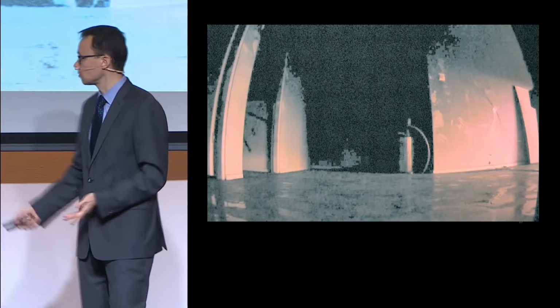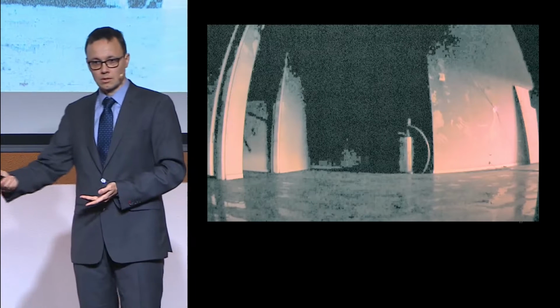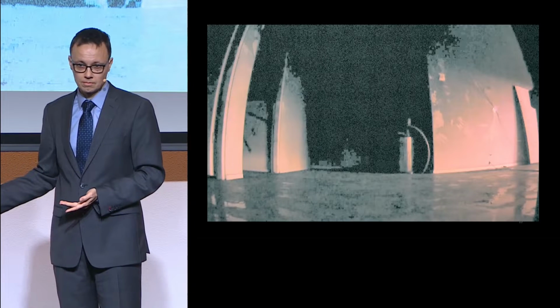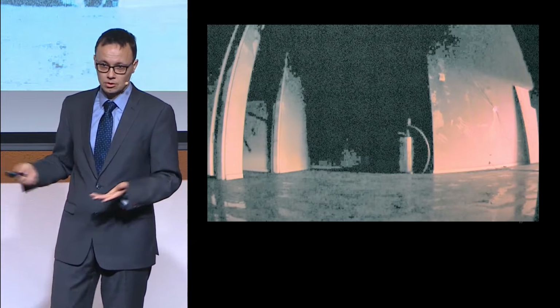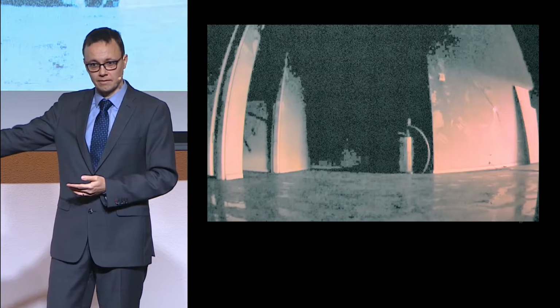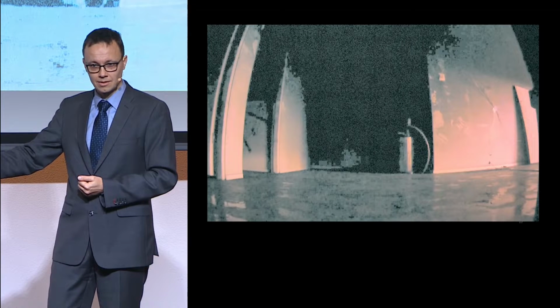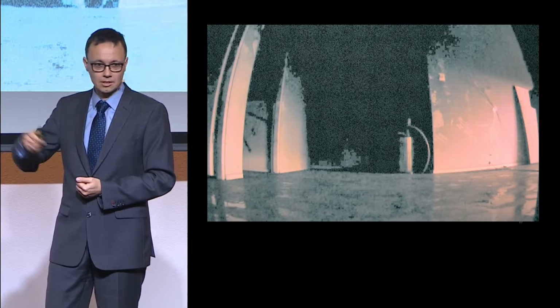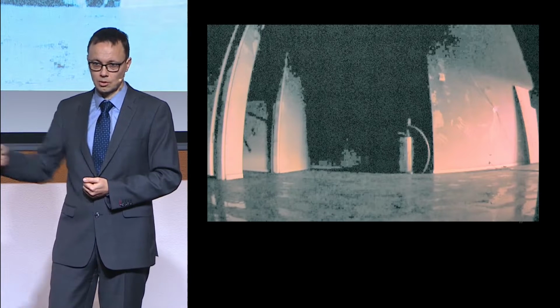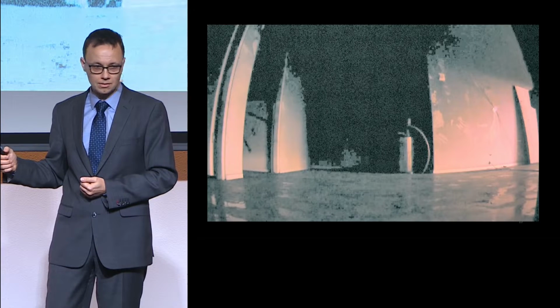Okay, thinking we have a door of about 2 square meters. Okay, about. So 100 Pascal means we have how many kilos? 10 kilos per square meter, 20 kilos to the handle.